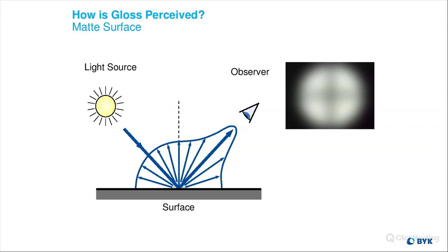Okay. I'll jump in here too. Especially with transparent products, making sure you measure and compare the same thicknesses is also pretty important, because if you measure different thicknesses, let's say a 6 mil thick piece of transparent material versus a 3 mil thick piece, because of the reflections that you're getting off of both the surface and the bottom of that material, you'll get different results. So it's always important to compare apples to apples. In that case, it would be comparing the same thicknesses to the same thicknesses. That's always something to keep in mind when you're doing that type of measurement. Nice.